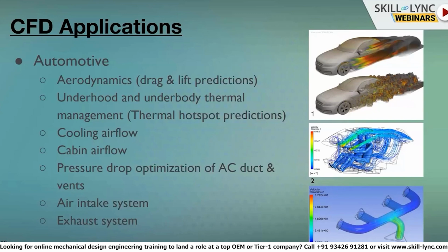So the vent shape also he has to design so that the air flows maximally expanded in all directions. So those are some critical areas wherein a CFD engineer working in automotive applications has to think and focus. And there are others, like the air intake system and exhaust system. Those are system level components wherein one has to work on air intake system pressure drop optimization or flow uniformity index, or exhaust system temperature predictions due to hot gases flowing through it. So these are the applications related to automotive.